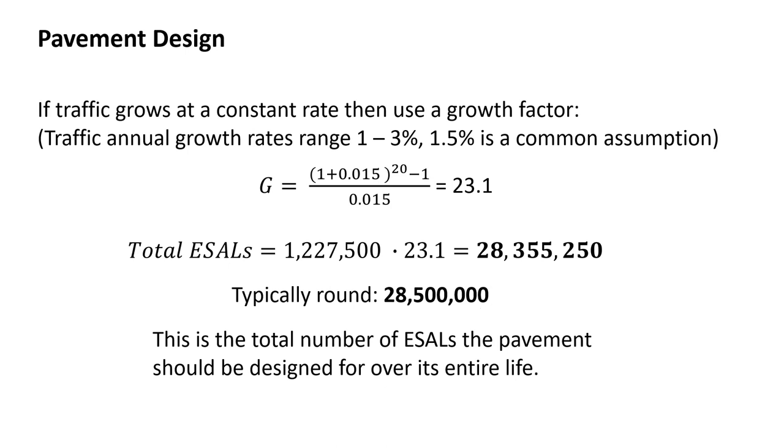So that's our intro to traffic and how we're going to use it in design. The first big important piece is how many ESALs do you have? This is how we get there and find it. So you hopefully understand how an ESAL is calculated. You're almost never going to have to do it per vehicle and calculate the axles themselves and use those tables. You're almost always going to use some average value someone gave you.